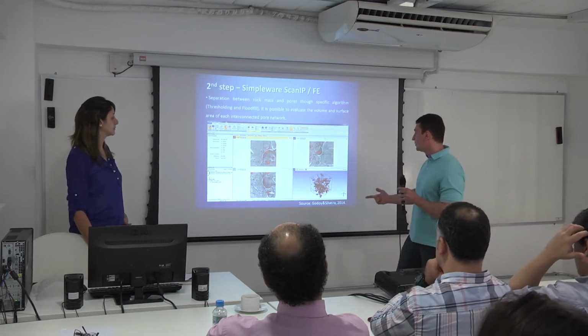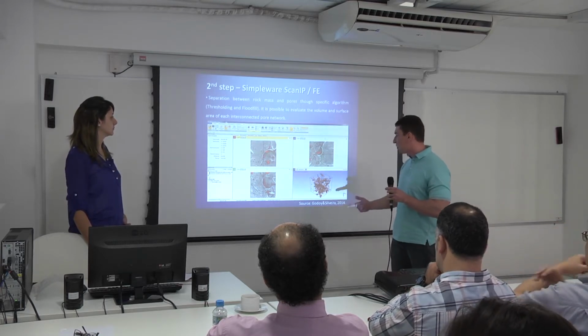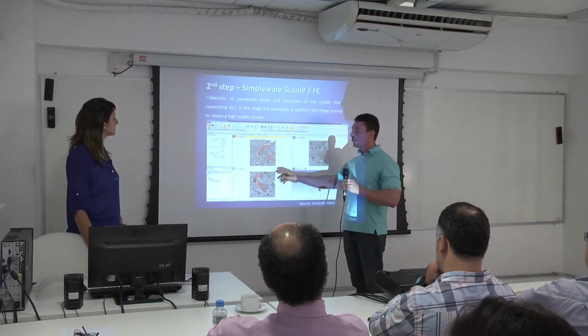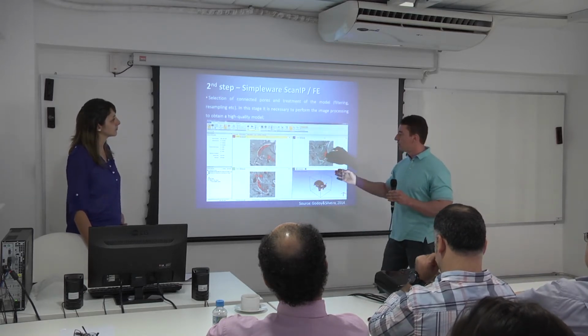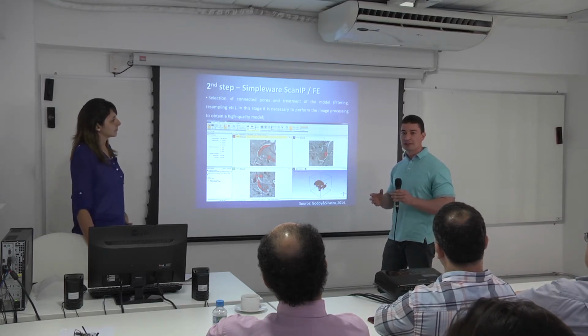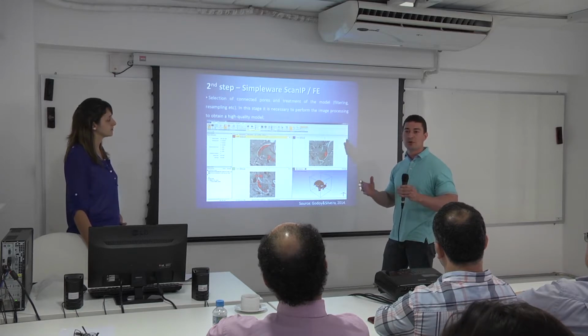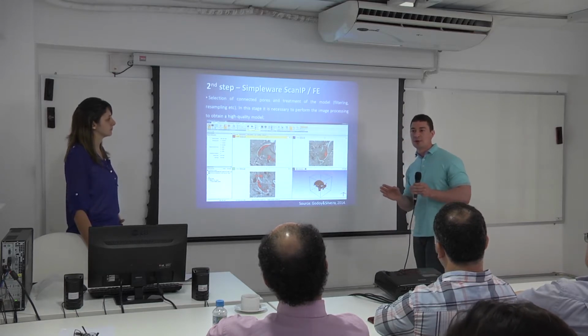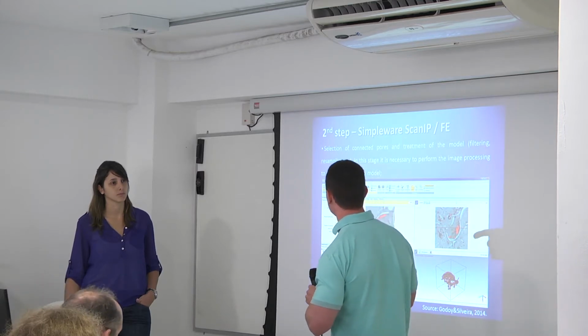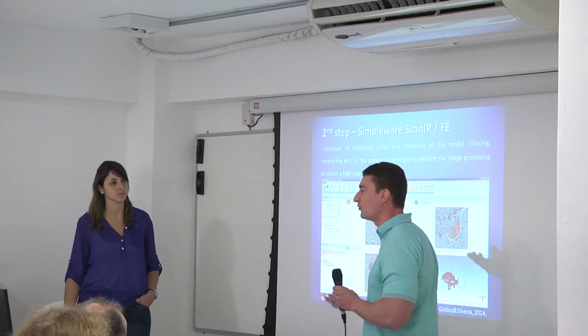And as you can see, you can reconstruct the entire pores. Then we can resample. For example, when you are working with a sample with a very high resolution, the data is too huge. You have to work with a file that's not too huge. So we are working here to resample with a downsampling factor of 3.